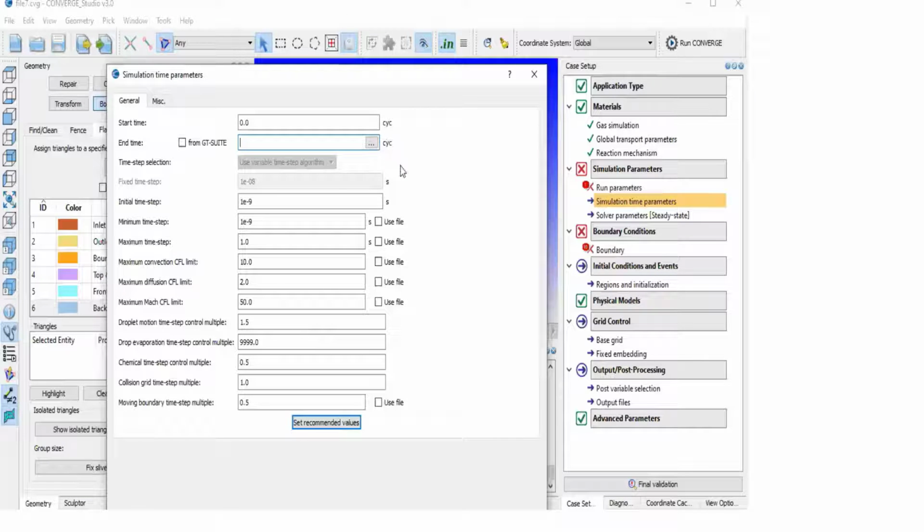Why? See, when you're setting up, times come in three forms. One is in cycles, when you're running a steady state. One is in seconds, when you're running a transient case. The third one is crank angle based, when you're running IC engines or turbomachinery where the fluid is rotating, or some component is rotating. Okay, so let's say for cycles I want to keep 15,000, for example.